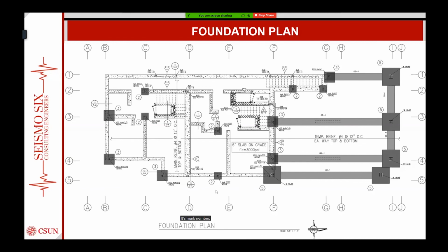A lot of those are for interior columns, like our 4 by 4 posts, our 4 by 4 HSSs, or our 6 by 6 HSSs. The larger pad footings are more for the moment frames. Okay, thank you. Oh, sorry, I'm cutting out. Oh, I got the drift, so it's okay.